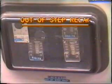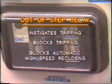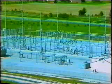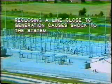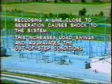As we have already seen, the out-of-step relay may be used in several ways. That is, 1, to instigate tripping, 2, to block tripping, 3, to block automatic high-speed reclosing. Now, why would we want to block the reclosing action when we have earlier pointed out that fast reclosure actually assists stability? Well, this is true, but once the system has become unstable and the out-of-step conditions exist, then reclosing a line close to a source of generation may well cause a shock to the system that increases the load swings and aggravates the out-of-step conditions.